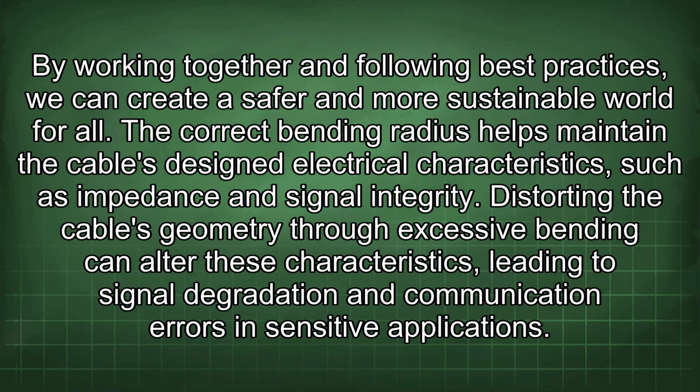for all. The correct bending radius helps maintain the cable's designed electrical characteristics, such as impedance and signal integrity. Distorting the cable's geometry through excessive bending can alter these characteristics, leading to signal degradation and communication errors in sensitive applications.